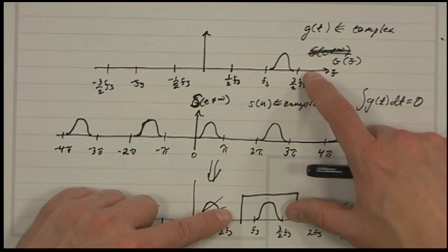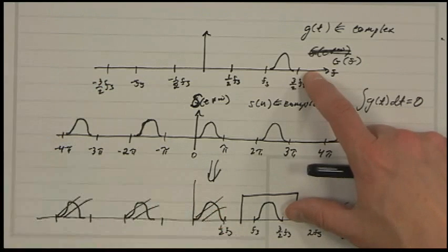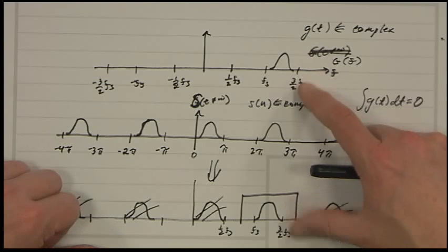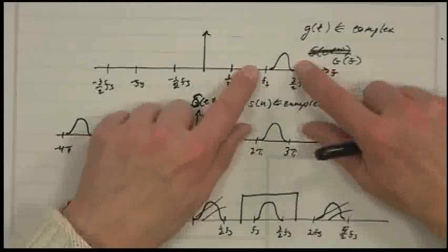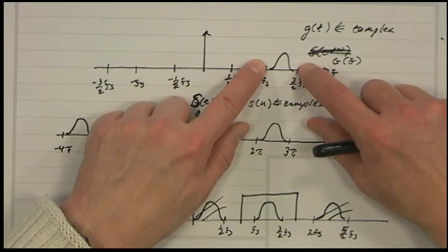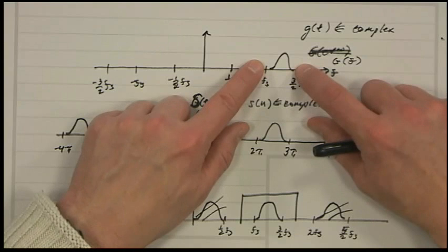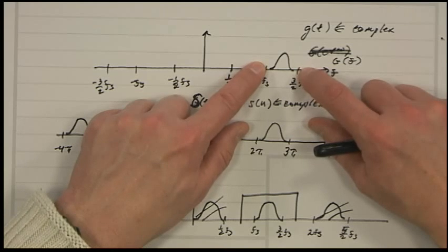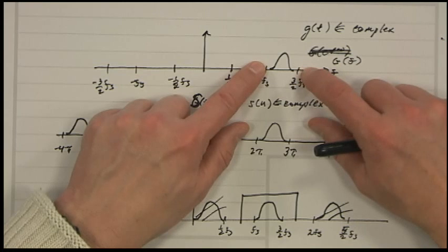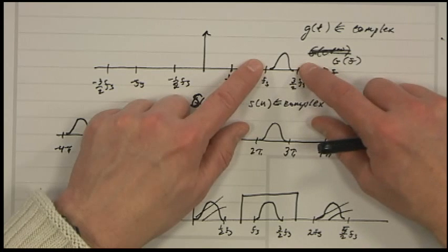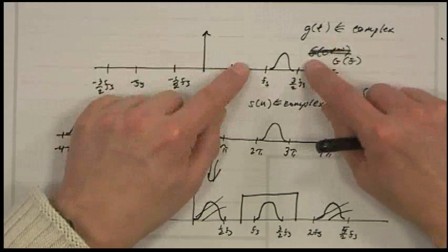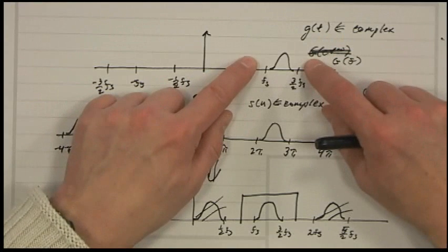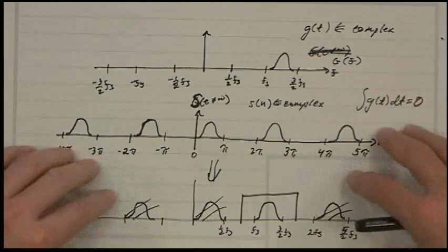What if you do not know the signal frequency? Then you've got a problem. Yeah, that's what I mean. Yeah, so the real key issue in sampling is that you have a constraint on the signal that you know it has some limited bandwidth, and you know where that is. The classical formulation of Nyquist sampling is that it's band limited and you know what the range of non-zero frequencies is. There could be an extended version of that where you have to estimate the range of non-zero frequencies. But yeah, it's a good question.